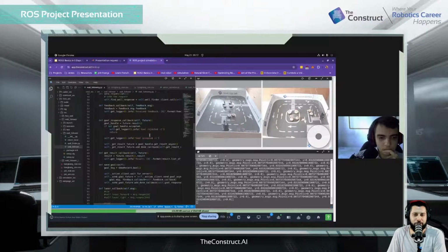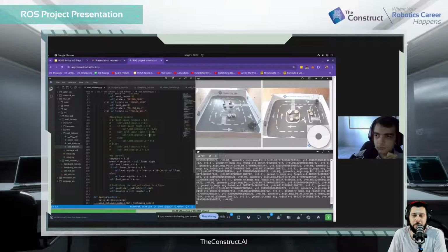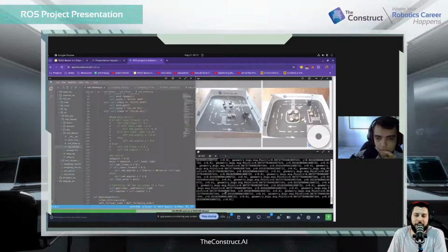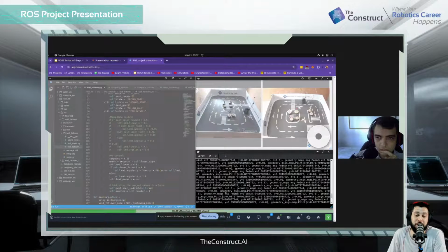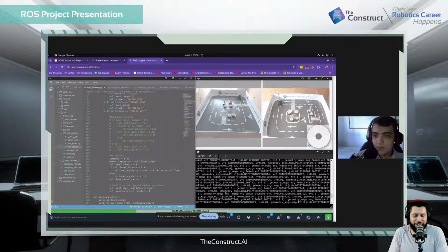I was curious about the last step here, the returning of the odometry points once the action is completed. You mentioned that the odometry drifts, and yes, it does. It also probably explains why on the real robot you saw that kind of straight line, and then it flipped a little.